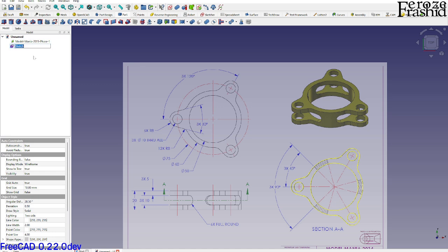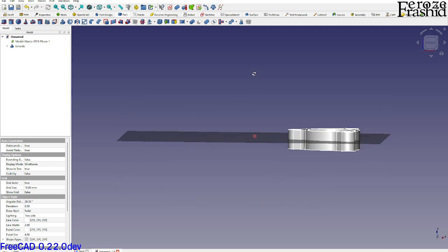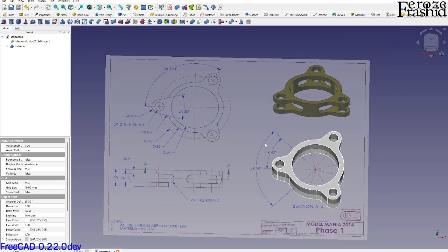I'm gonna go ahead and rename that. Okay, and I want to extrude that for 20 millimeters right now, and maybe make it symmetric. So this is going half and half, up and bottom. All right, now let's talk about these gaps that we have.